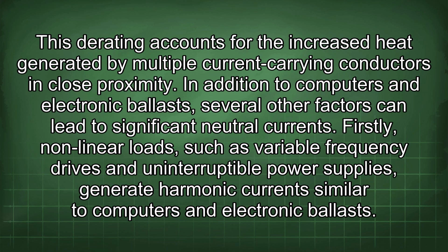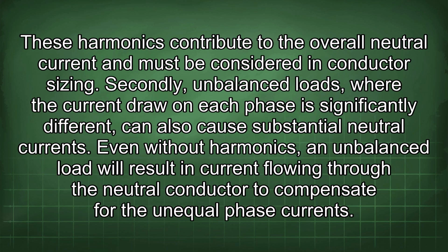In addition to computers and electronic ballasts, several other factors can lead to significant neutral currents. Firstly, nonlinear loads, such as variable frequency drives and uninterruptible power supplies, generate harmonic currents similar to computers and electronic ballasts. These harmonics contribute to the overall neutral current and must be considered in conductor sizing.